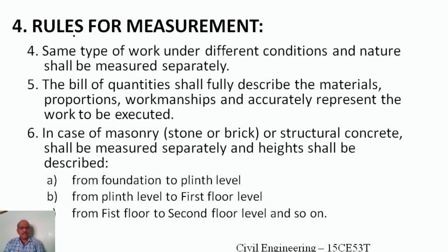And the next one is the bill of quantities shall fully describe the material, proportion, workmanship, and accurately represent the work to be executed. In a BOQ, we shall mention the description of the material, proportions, and workmanship involved in the description. In case of masonry, brick, stone or structural concrete shall be measured separately, and height shall be described. So as we have discussed in the fourth point, the same thing will be there here.